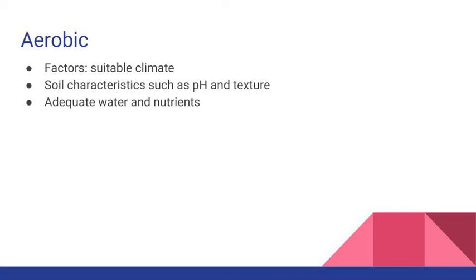Also, for in situ treatment, it does not require excavation of the contaminated site, compared to other technologies such as thermal desorption or incineration, which usually require excavation and heating, thermal enhanced recovery, chemical treatment, and in situ soil flushing, which may also require further treatment of the flushed water. Biological remediation is a cost-effective treatment of non-halogenated SVOCs.